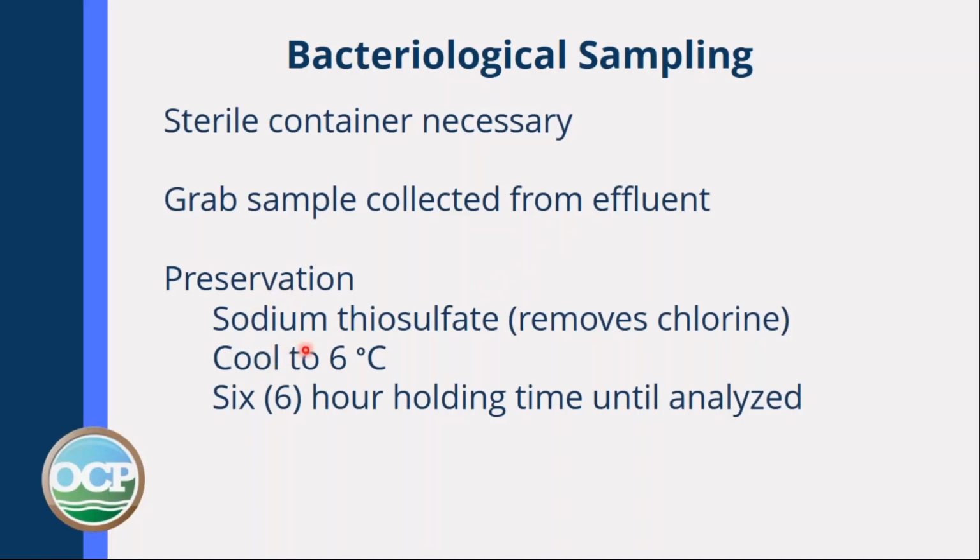Preservation, again, you're going to cool it to 6 degrees. You have a 6-hour holding time. That is 6 hours from taking the sample until you begin to culture those bacteria. And anytime you take a sample for coliforms, the container should be sealed. If it's not sealed, don't use it.